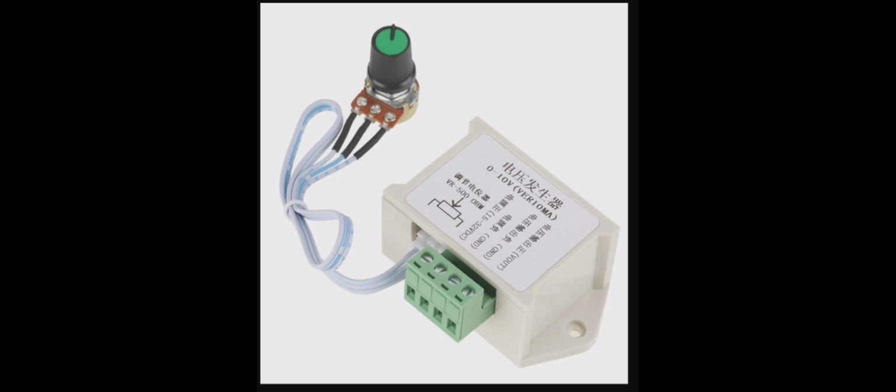Now, what is the summary of analog output? The analog output is predominantly used to control actuators, valves and motors in the industrial environment. It controls the field devices in the form of a 4 to 20 milliampere signal or 0 to 10 volt as per their requirement. The standard analog output ranges are 0 to 5 volt, 0 to 10 volt, 4 to 20 milliampere and 0 to 20 milliampere. Now let's have a quick look at DI, DO, AI and AO, that is, analog signals and digital signals.